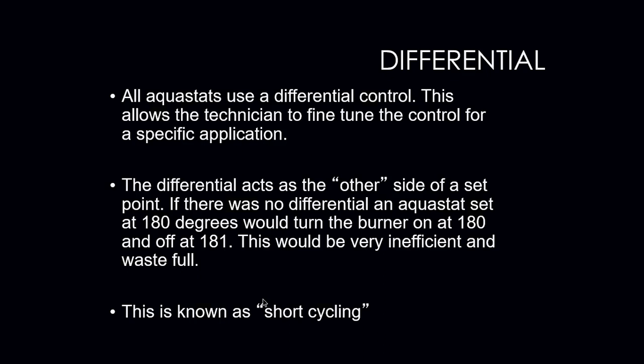And that would actually be very wasteful and would actually cause the boiler to short cycle. We want to have a differential setting on our boilers. We do not want the burners to be turning on and off, on and off, on and off constantly. If that was to happen, we can actually risk damaging the burner, boiler, and all the components on it. So we want to have a differential.